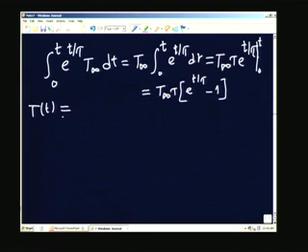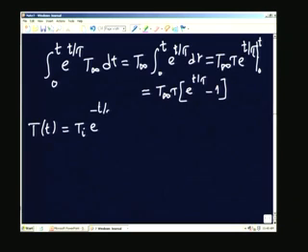So, if I put it back into the general solution of the problem, T as a function of time, I have T I e to the power of minus t by tau plus e to the power of minus t by tau divided by tau multiplied by that integral.